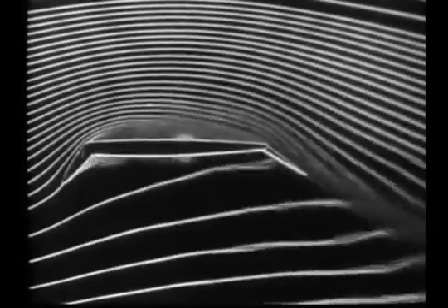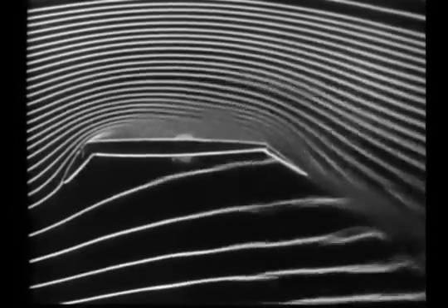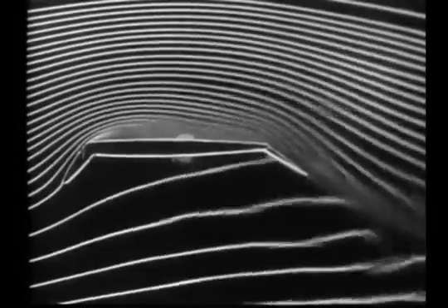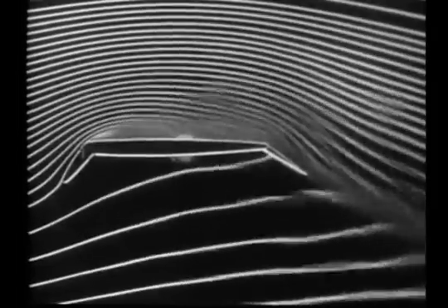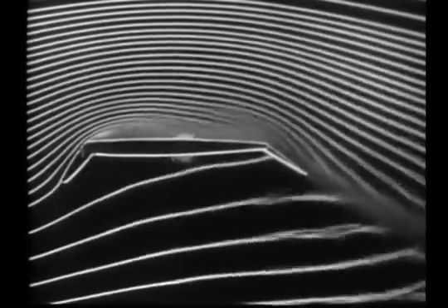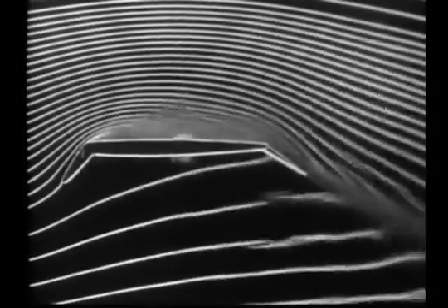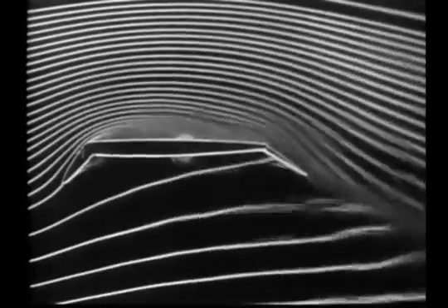By blowing air over the trailing edge flap, the separation in this region is suppressed and circulation of the profile increased. This increase in circulation so alters the flow field that the adverse gradient at the leading edge vanishes, and separation at that point is also suppressed. Separation at the leading edge flap break still exists because of the small radius of curvature at this point. To approach the potential flow pattern, it is necessary to overcome this separation by diverting some of the air now being blown over the trailing edge and to blow it over the leading edge flap break.